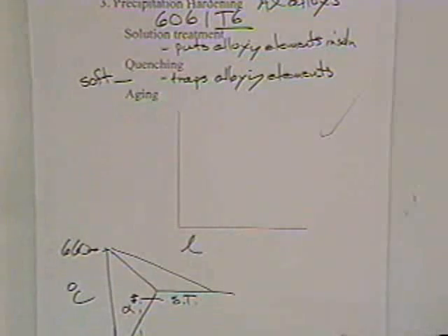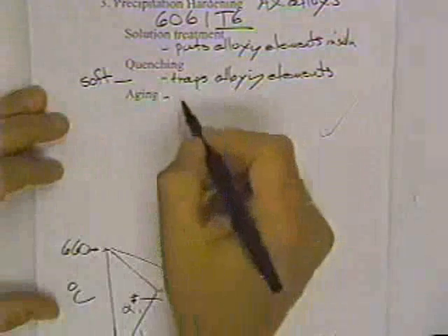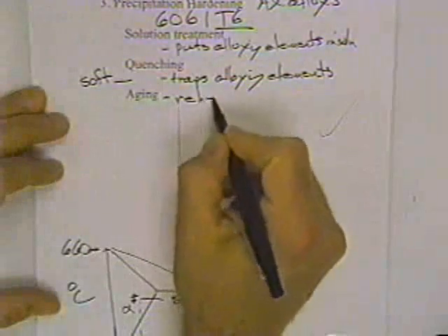Aluminum's face-centered cubic, and so in fact, after you've quenched, the material is soft and ductile. The aircraft industry uses this for their rivets. They solution treat them, quench them, store them in a refrigerator till when they're ready to use them, put them on the plane, and then they allow them to strengthen naturally during the process as they warm up to room temperature.